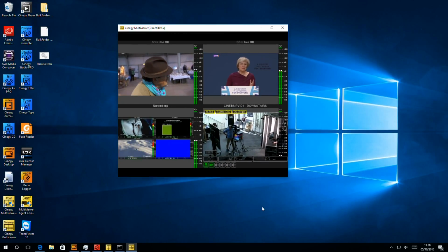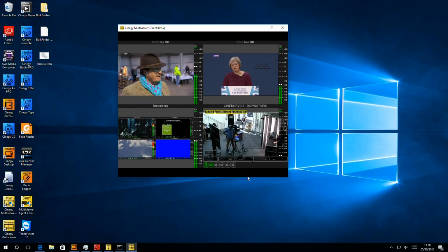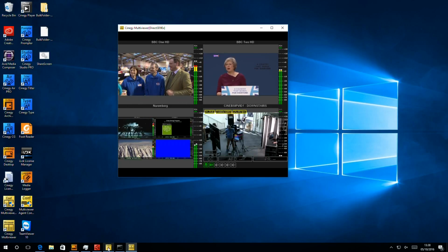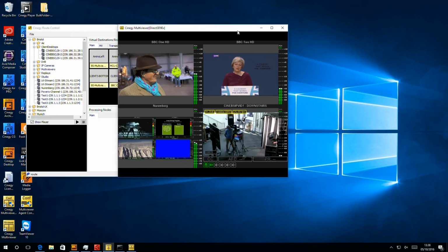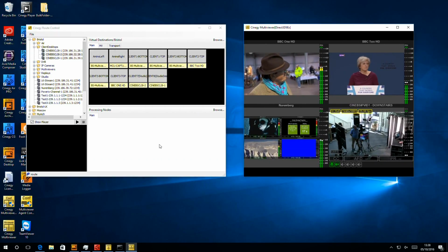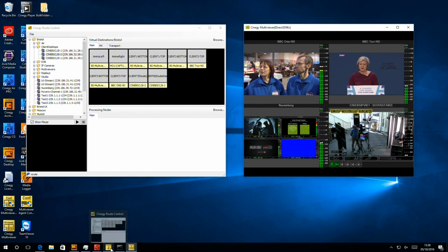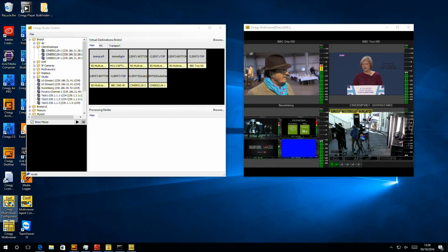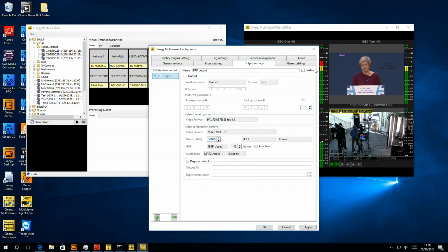But what's really interesting is when you want to say, hey, this is lovely, but let's also get this out on IP. So now I'm going to do the final part of the demo, which is I'm going to make sure that I've got an IP reserved to display on the screen behind me. And then I'm going to pop over to Cinegy Multiviewer, and I'm going to enable RTP Output. So if I click Enable, Multicast, and then the address that's been assigned to me already is